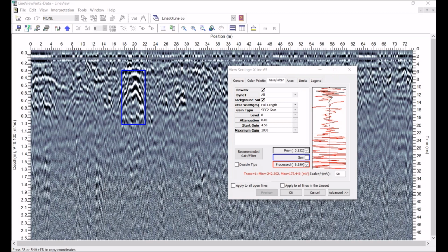Metallic artifacts deeply buried or located in walls won't produce ringy responses anymore. So how can we find them? What I would be more likely to do is actually turn the gain off. I think what you're getting at is we know that metallic objects give you 100% reflection coefficient. So a metal object should give you the strongest response of any object in the subsurface. To try to recognize that, as you say, a metal object that's very shallow will ring.